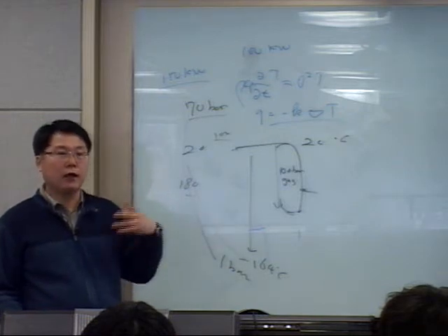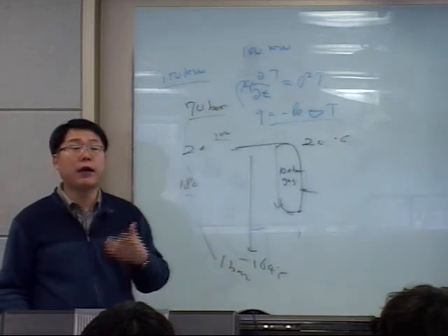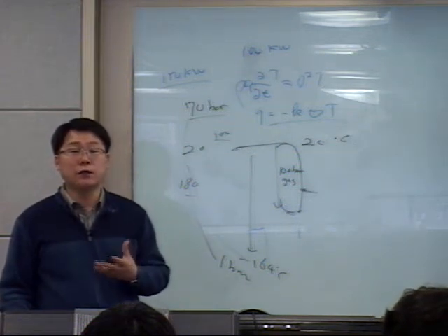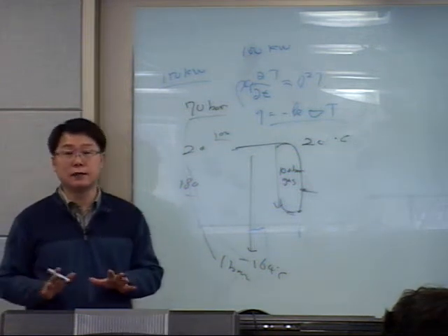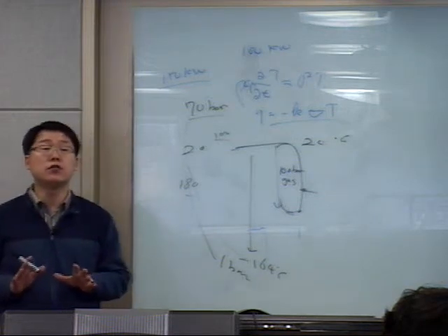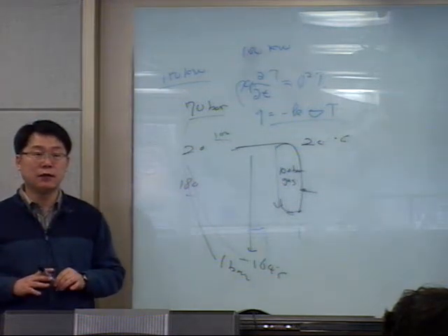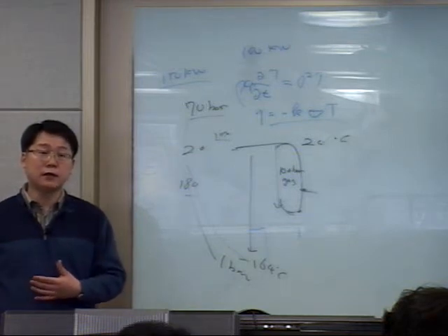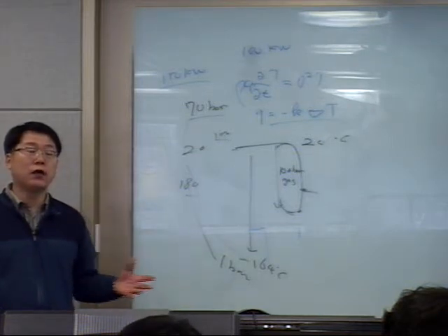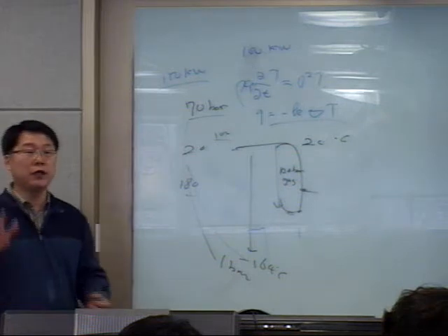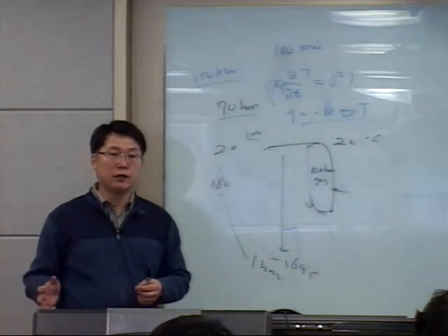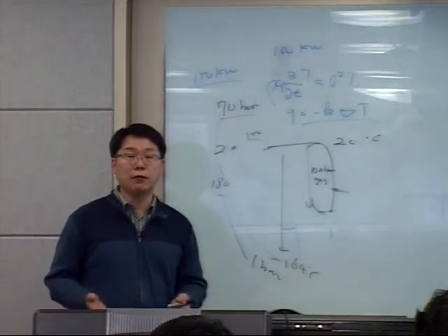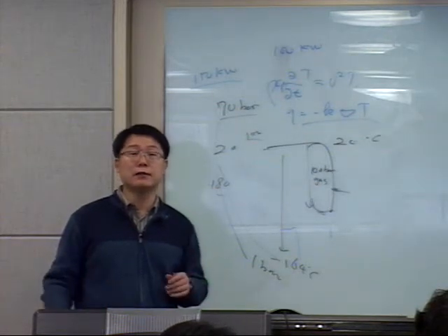All right. Phase change. Making LNG from gaseous natural gas is an energy consuming process. That means the latent heat is significantly high, so it's very hard to increase or decrease the temperature or pressure of a boiling system or condensing system.